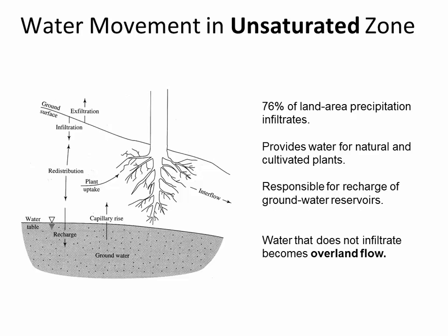Recharge is what we call it when infiltration is increasing the depth of the saturated zone. And any water that isn't taken up by plants or moving sideways through the soil, anything that actually doesn't make it underground is what's going to be the overland flow, the runoff. It's going to be the rainfall excess, or overland flow is what isn't infiltrating. And so that's why we're so interested in infiltration, is just because ultimately we want to say how big that culvert has to be or how deep the water will be in a stream.